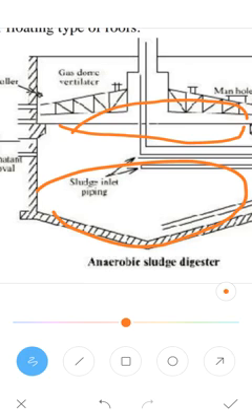The combination of standard and high rate digestion can be achieved in two stages of digestion. The first stage is the standard rate sludge process, and the second stage digester mainly separates the digested solids from the supernatant liquor.